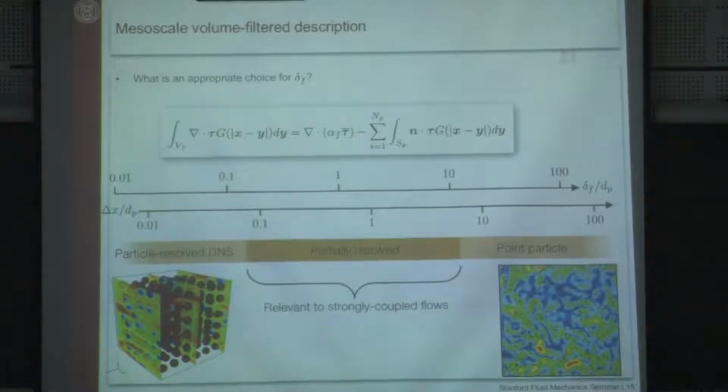We're hoping that we can bring our mesh resolution close to the particle scale, not below the particle scale, but close enough that we can explicitly capture the clustering phenomenon on our grid without having to model it, without having to re-inject it in the form of modeling assumptions.